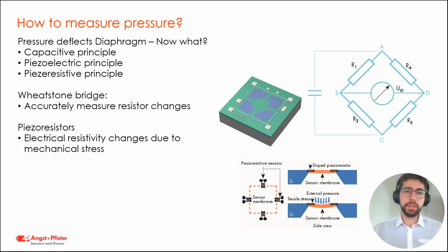The piezoelectrical principle employs piezo crystals. These crystals generate a voltage when force is applied to them. This makes them suitable for high-frequency applications as they accurately measure pressure changes. They are not really suited to measure static or quasi-static pressure. Not to be confused with the piezoelectric principle, lastly, today we will be looking into the piezoresistive principle.